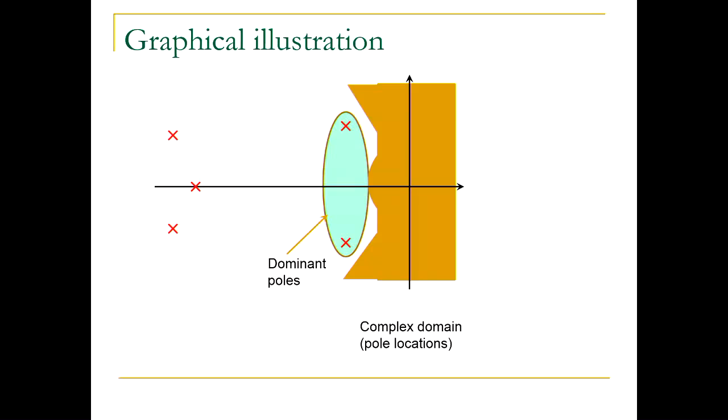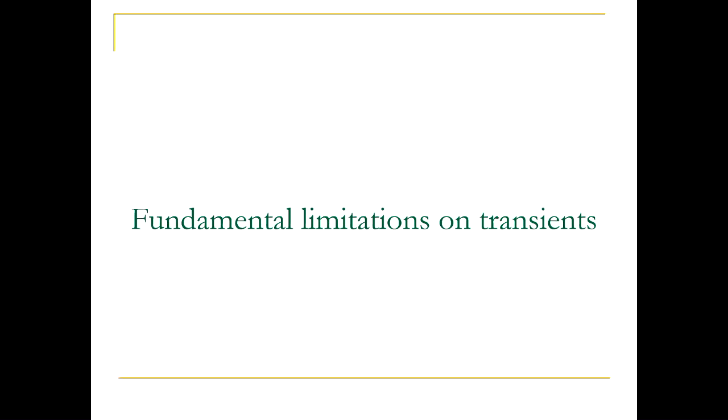All right, so what are the dominant poles? Well, suppose that you translated your overshoot, settling time and rise time into a region like this, then if your system is fifth order, what you can do is place two poles close to the imaginary axis, and all other poles you move far away. Then those rules of thumb would give you good results, right? This is often a design technique that you would follow. It's not universal, but sometimes it's possible to use it, okay?